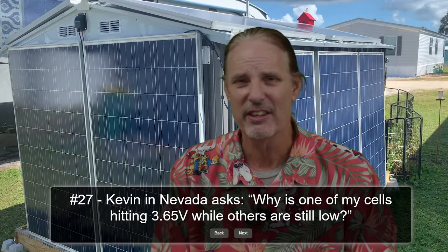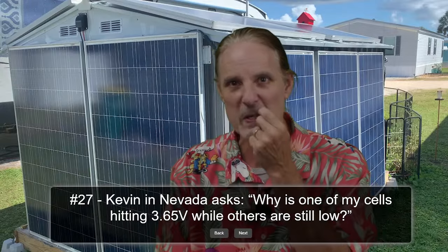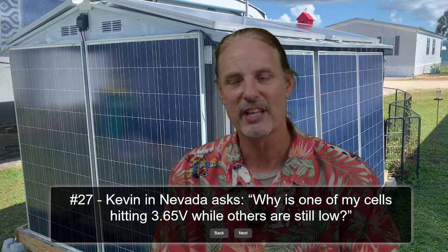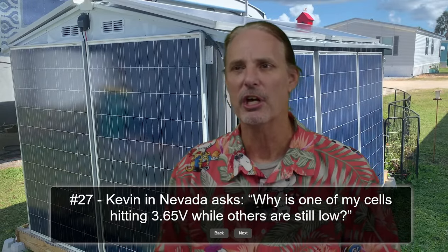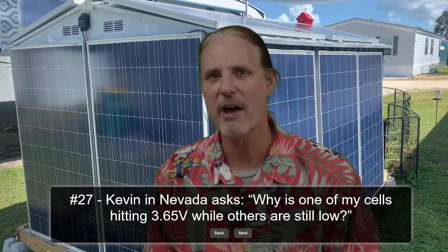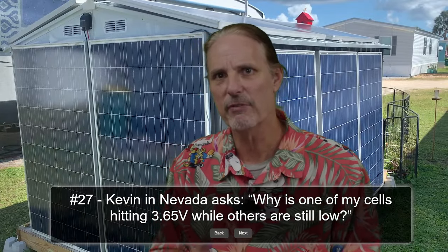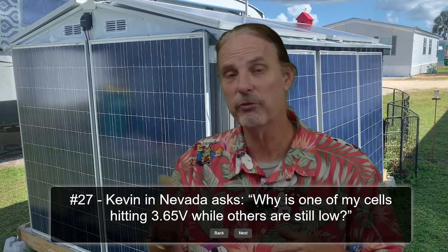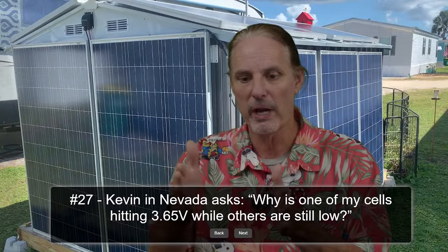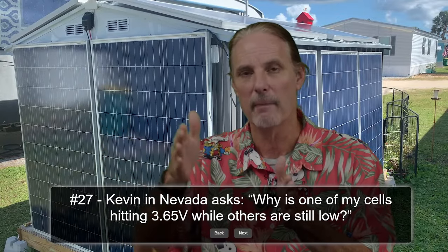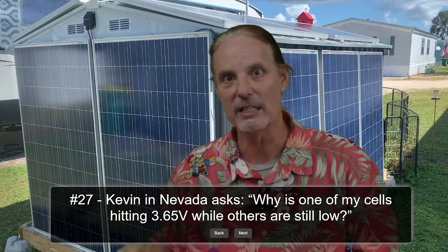And it really is going to take them a few more years of building balancers where you can say things like charge to 58 volts, and the BMS is smart enough to know that I need to slow down as I start approaching the 55 and 56 range in order to give those cells enough time to balance, and hopefully some AI logic in there that would say, look, based on the rate that I'm charging and discharging, I'm going to have 30 or 40 minutes of this kind of sun, and I need to do this or I need to do that.